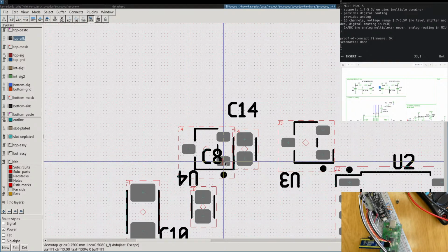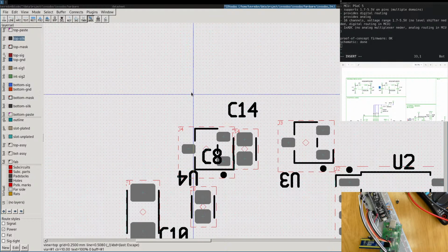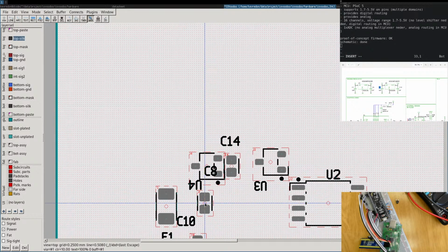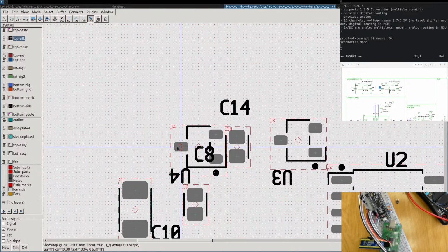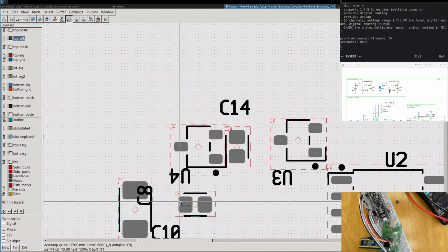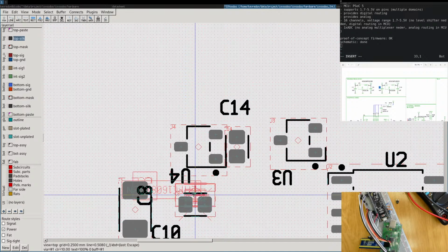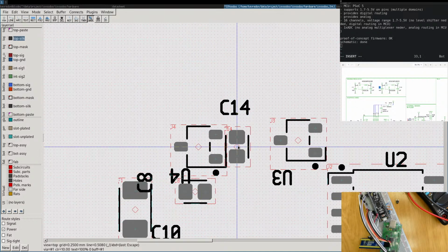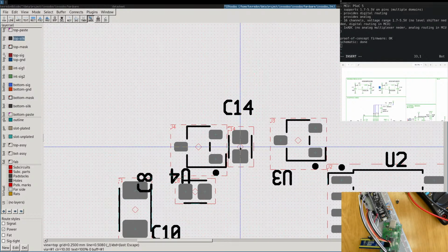It is less important because there will be thick traces to the ground everywhere, so the resistance will not be high on the trace, and as for coupling. But most importantly, this one. So we will have it somewhere like this, exactly. That's the input, that's the output. Very close.